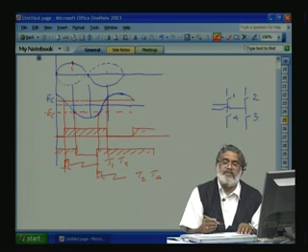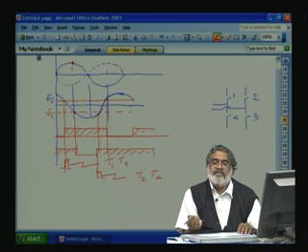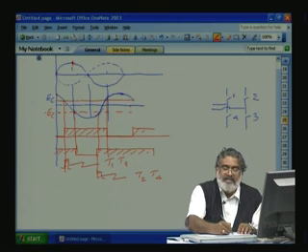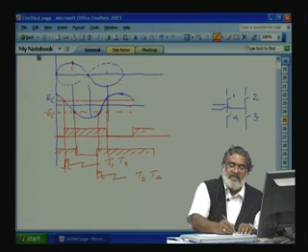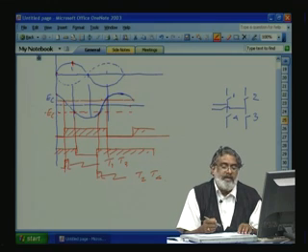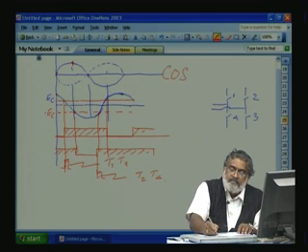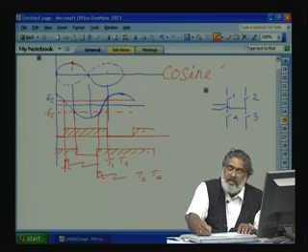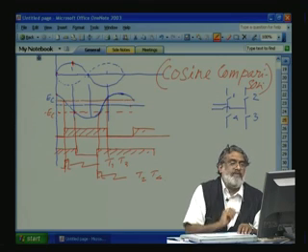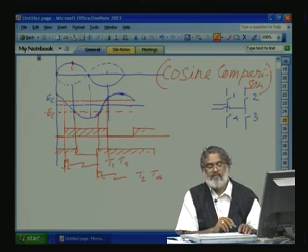That means when EC is maximum, output is maximum. EC being maximum here means automatically the firing angle is 0, so the output will be maximum, and the variation of EC is proportional to cos alpha. So, it is compared with the cos alpha waveform. This way we can have the output voltage waveform. Many textbooks use circuits to generate this cosine comparison, that is, the control voltage is compared with a cosine wave derived from our step down mains waveform.